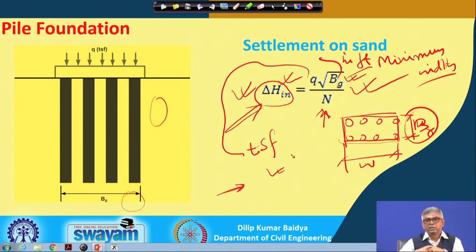Similarly, another model is that if the pile is driven in compressible soil and finally rests on a stiff soil, then it will be modeled as an equivalent raft at the pile tip, and based on that model one can calculate the delta sigma, the effective vertical stress, and then finally using that log formula one can find the consolidation settlement.